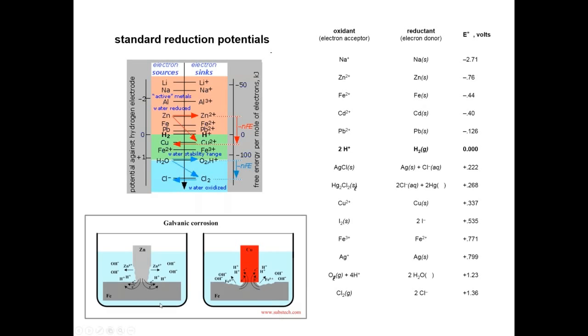What you essentially have to look at is the flow of electrons. So a simple galvanic corrosion diagram, as shown here, shows that zinc essentially donates the electrons. On the other hand, with iron and copper, it's the other way around. So in other words, iron is corroded more than copper. On the other hand, zinc is corroded more than iron. So I hope that simplifies things if you are new to corrosion.